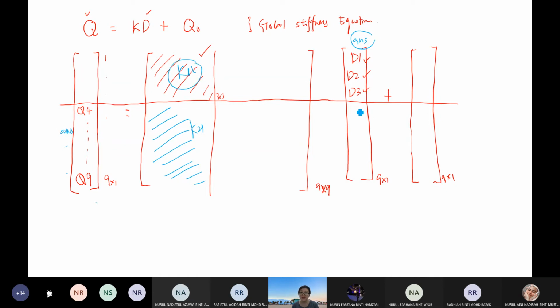So now we are going to find this K11 first. You need to make sure that these are all zero. If by any chance this has values, then the columns associated with that row, you need to find also. For example, if row 5 has a value, then for column number 5 you need to determine those elements of the stiffness matrix too, but not for this case. So now we are very clear. If D has 3 unknowns, we only need to find the 3 times 3 stiffness matrix to solve for D.